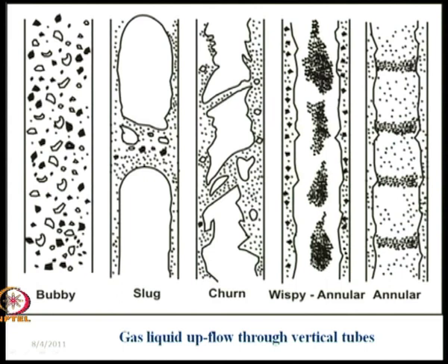So, therefore, the annular flow can be characterized by a smooth interface or an undulating interface, depending upon the relative velocity of the two phases. Its main characteristic is a continuous liquid film on the wall and a continuous gas core between the liquid films. There may or may not be droplets or wisps of liquid in the gas core. Some researchers have tried to differentiate between wispy annular and annular flow, but we are not going to do this for our particular purpose.